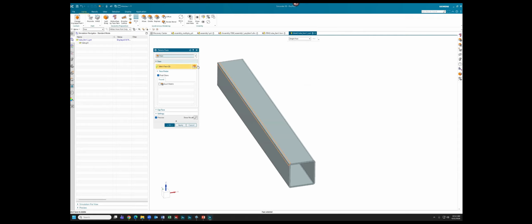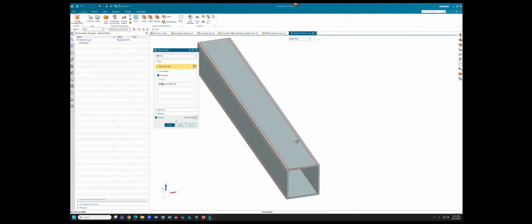And what's really great is these synchronous modeling tools also have this face finder capability. So for example, I just have one fillet radii that I've selected, and then I can leverage the face finder, and it's going to automatically select all of those equivalent fillet radii. So that's just going to save you clicks. And that's something that I've always really appreciated about SimCenter as well, is how it can save you a lot of clicks by leveraging some of the really powerful selection tools within the software. And if you've done a lot of preprocessor and mesh setup, you know, saving clicks can equate to a ton of time in the long run.